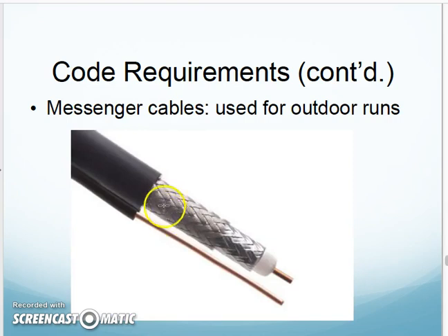Yeah, they give us all kinds of guidelines on where these need to be located in relationship to power lines and other things. Typically, the coax that is running from pole to pole or pole to house is a coax cable that has a messenger wire in it. And the messenger wire is there as structural support. That's a lot of tension on this cable and this conductor if I were trying to support it with that. So this is there to take up the load of the cable and try to protect this from breaking.